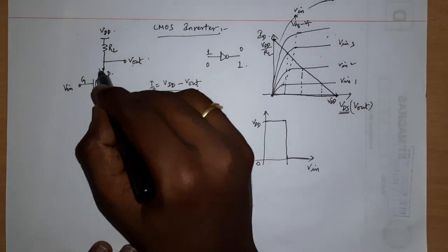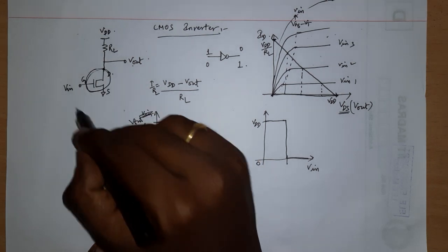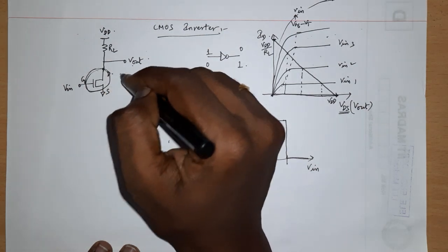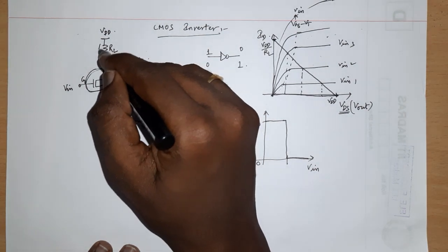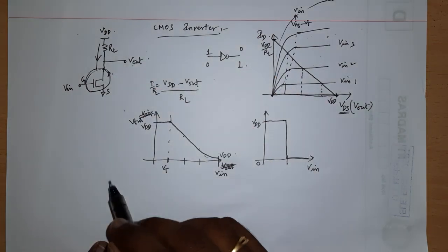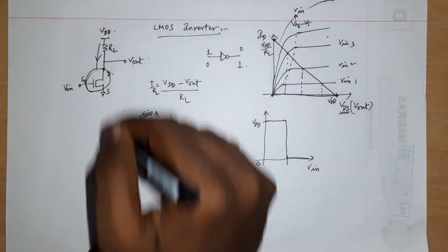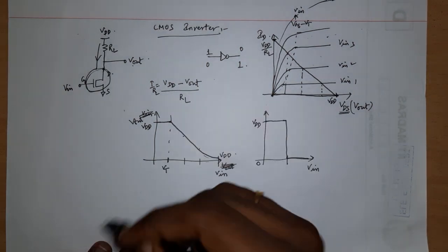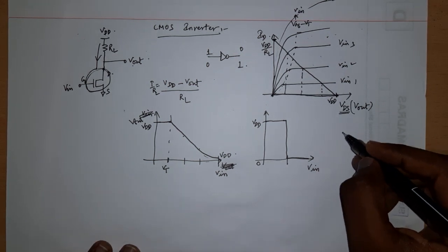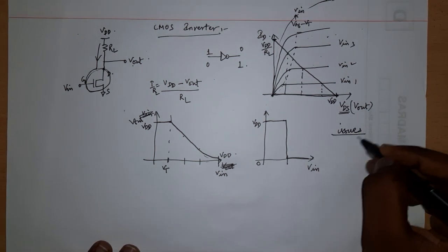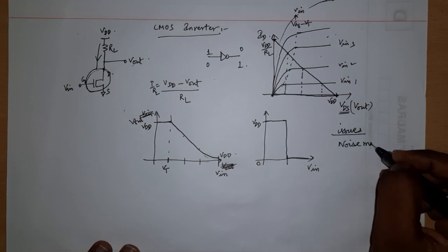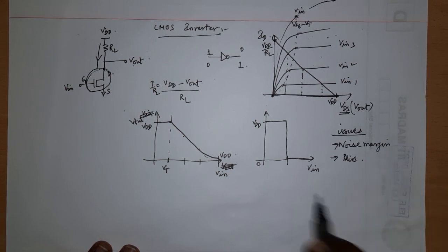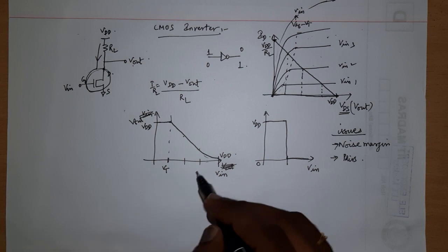And second thing is, when this transistor is on, to draw the output to 0, there is some kind of current flow from VDD to the ground, right? Which basically means some leakage current is existing. Okay, so it's a dynamic leakage. When the transistor is operating, there is some leakage current which I don't want. So you have issues with noise margin, you have issues with power dissipation. So we have to sort this out, and the main reason is this slope.